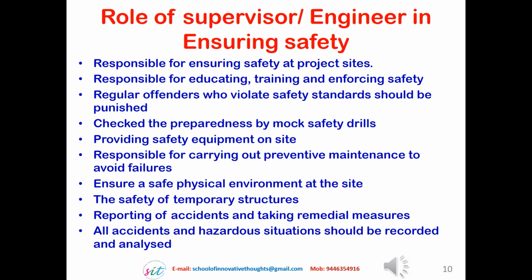In this slide, we discuss the role of the supervisor or the site engineer in ensuring safety at a project site. The supervisor or the engineer are the responsible persons who have to avoid accidents at a project site. We cannot fully entrust such responsibilities to the safety department. The safety department is only an agency to give support to the supervisors, engineers and workers, and it is the responsibility of the supervisor, engineer and worker to avoid accidents or hazardous situations at the project site.